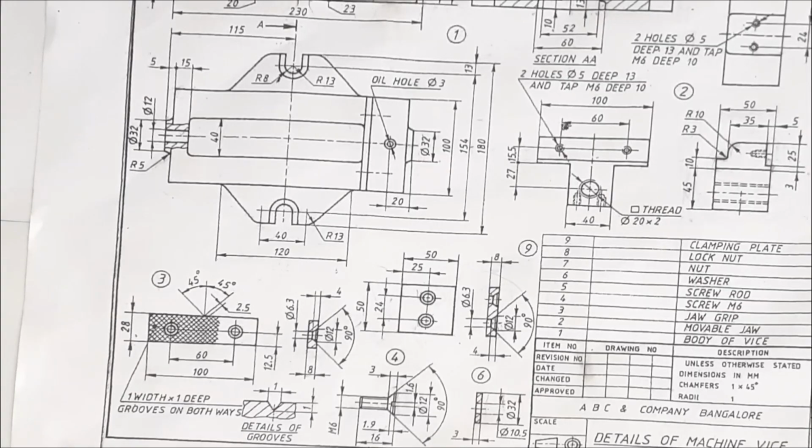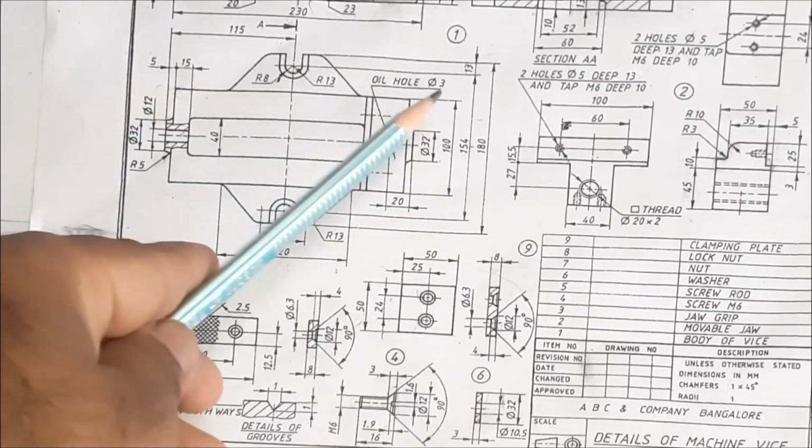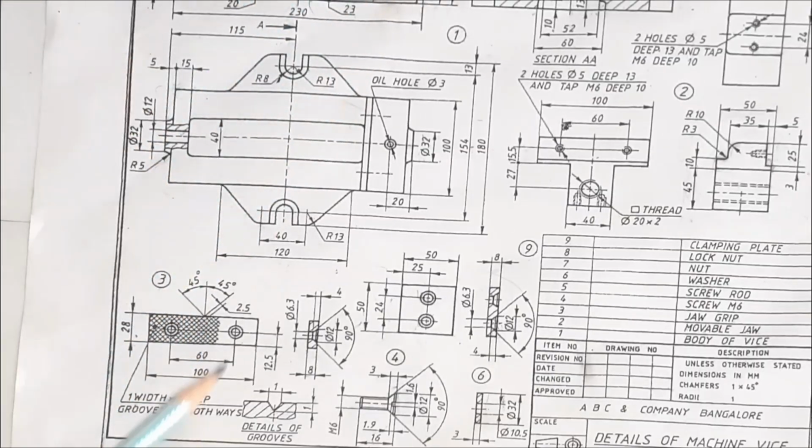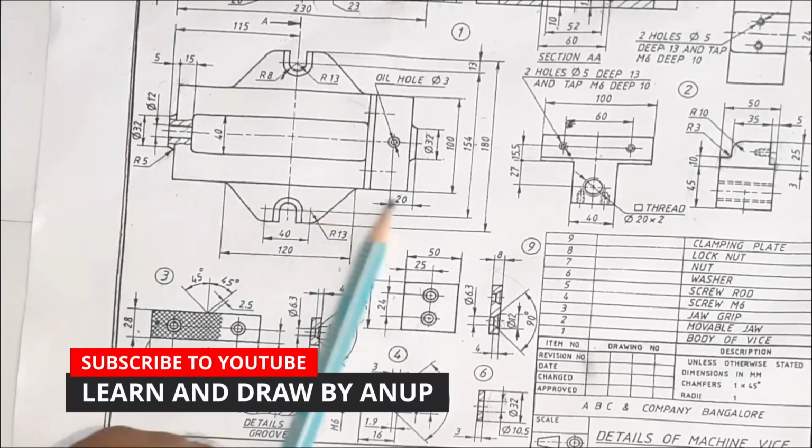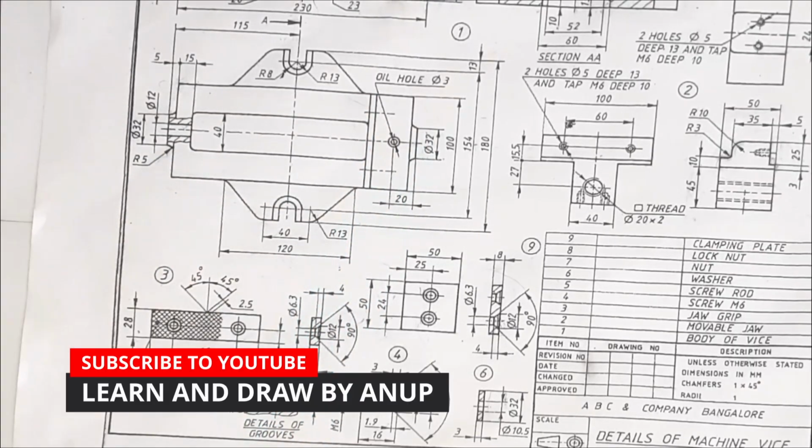First let's draw this outer rectangle. The length of this we will get from the projection lines of the front view, or you can measure it as 220 mm. So let's draw this outer rectangle, length of 220 and width of 100.